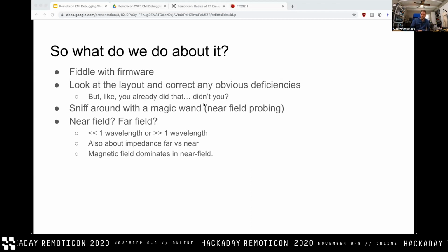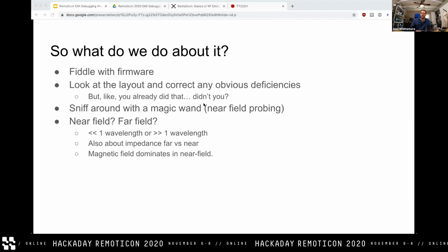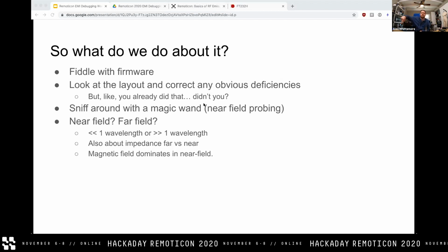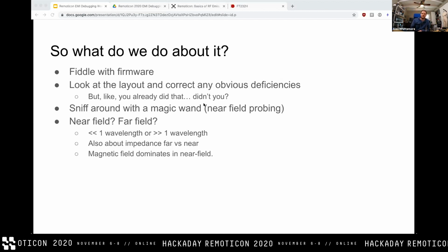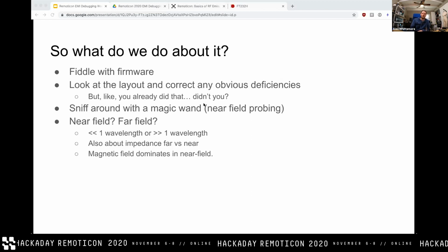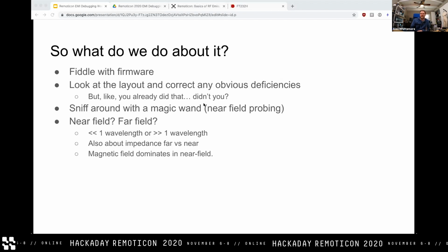But you can imagine things that cause signal integrity problems normally, like split ground planes where return current on a high-speed trace has to then go around in a big loop around your ground plane split and take a different path to the pin than the data trace itself. All of those sorts of situations can also cause RF emissions. So they can be somewhat easy to spot.